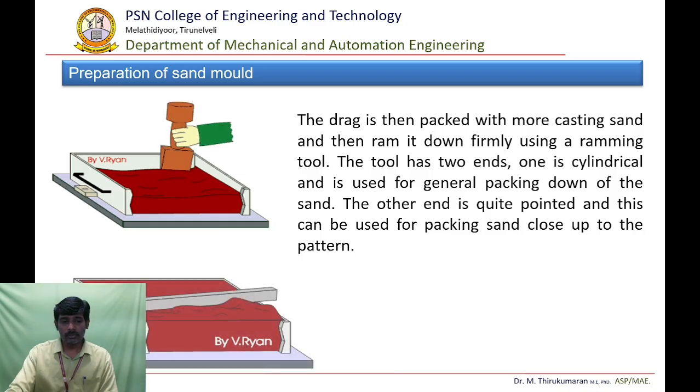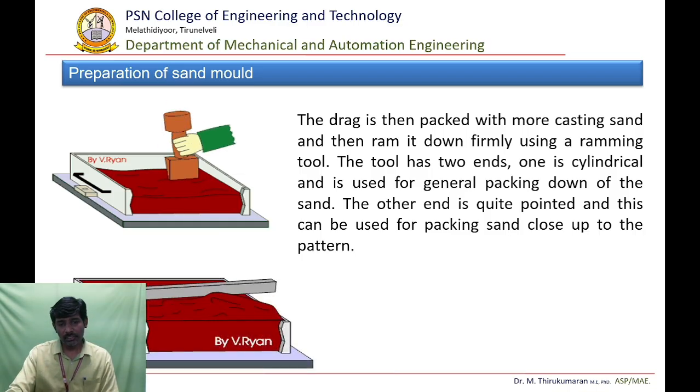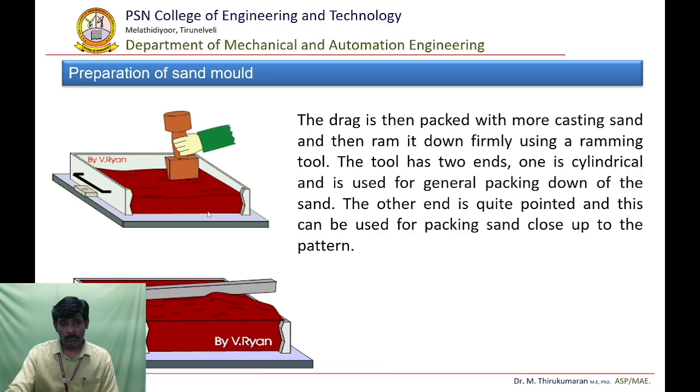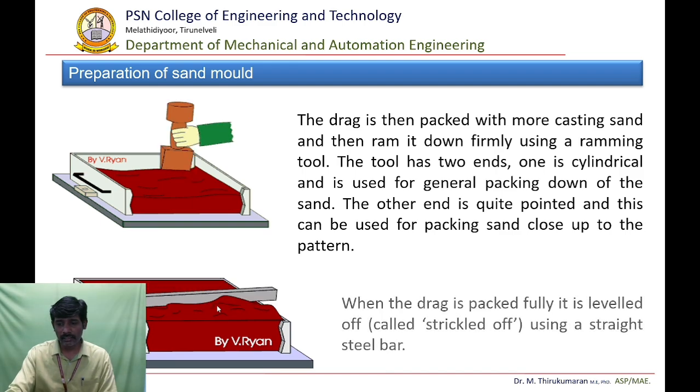Okay. So next, once we have packed with the rammer, the excess sand and excess material will be removed through a flat straight steel bar, which is called a strike-off bar.